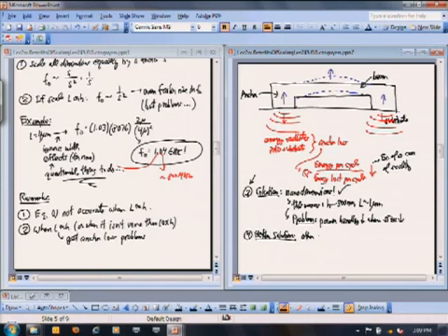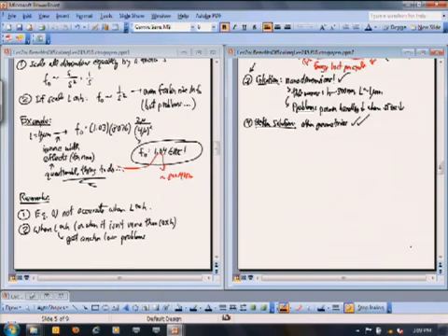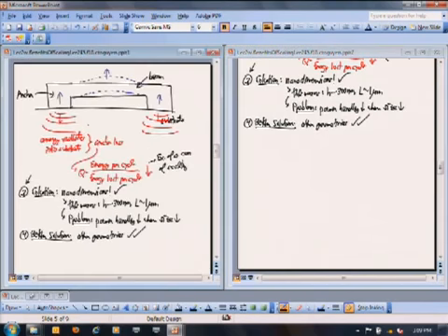So what do I mean by other geometries? So if I go back and I take a look at our problem, the fundamental problem here is that we're anchored at 2 locations as this beam is trying to contort up and down. Okay, so the problem is the anchors. The solution is to get rid of the anchors. Okay, and so how do you do that? You choose a mode shape. You could keep the beam, except use what's called a free beam. So one solution is to use a free beam.